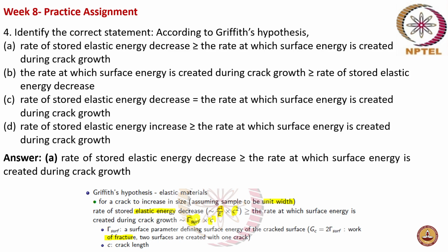When the crack surface has to grow and the separation between atoms has to take place, then this stored elastic energy should be taken up. The rate at which the elastic energy starts decreasing should be greater than or equal to the rate at which the surface energy is created, because when the crack is formed, a surface is created. When a surface is created, there's an energy associated with it.